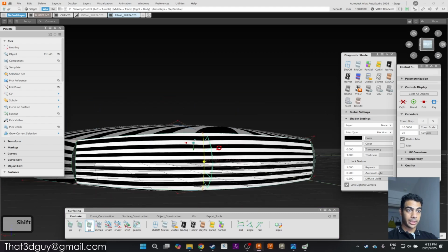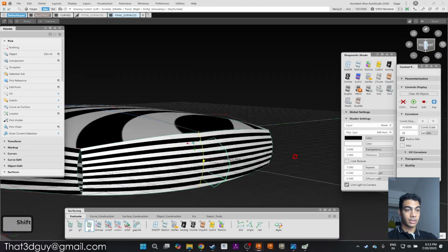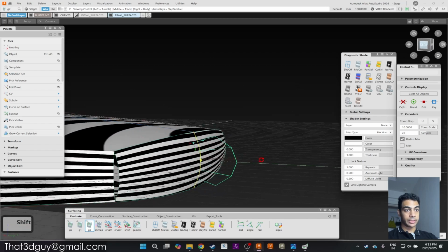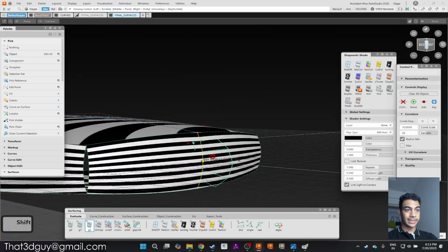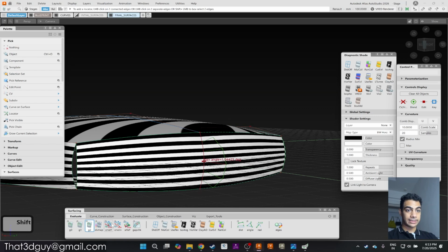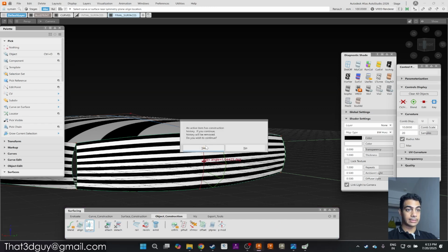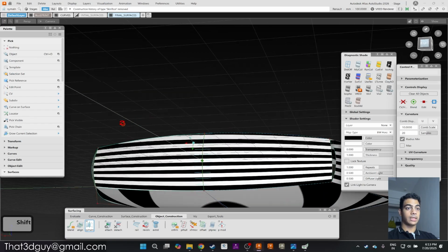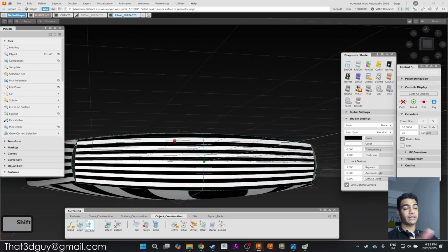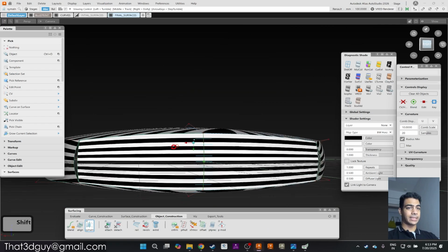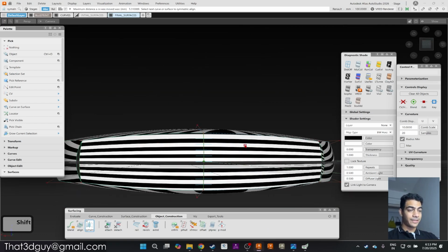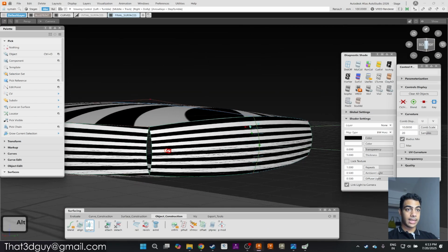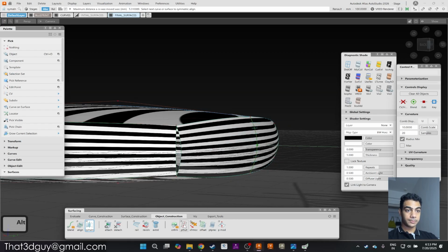Let's try to see over here, and we have a tangential error over here, which is 1.04 degrees. This is a very quick fix that we can do. We just have to basically use a symmetric align, and we have symmetric align here. We just place it at the center and it will align automatically. We could have done that manually, but I think for now, it's perfect.